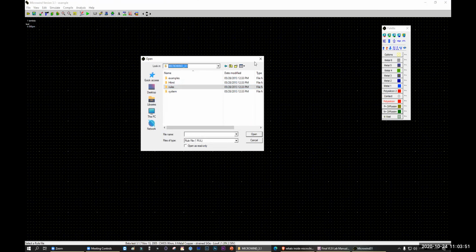We have to click CMOS 90 nano, CMOS 90N. That means it is the 90 nanometer rule. Why? Because all the calculation I am going to show you is for 90 nano. If you use different rules, your calculation will be different. Understood?